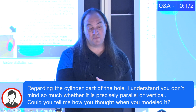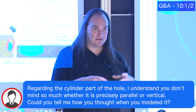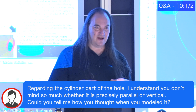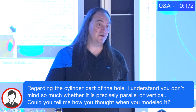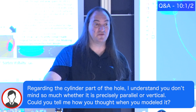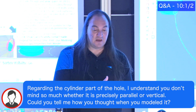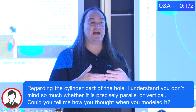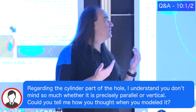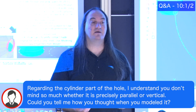In this case, when we made the disc a little bit smaller to make sure it didn't cut through, it turns out we made it too small in areas and you got some solar energy peeking through. If you go through all the slides, you'll see that happens in here. So again, it's a judgment call, but if you wanted to more closely match the exact geometry, you need more surfaces, more elements, more nodes to do it. So it again comes back to judgment.